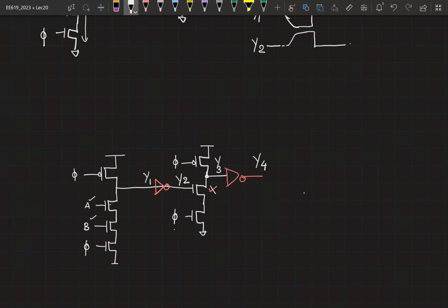So to answer that question, the question being asked is, this is anyways a NAND circuit that we were trying to implement. So if you have AND and an inverter here, it's already NAND. That is a very valid argument. I use this as a sample circuit. In actual cases, you have to imagine that the pull-down network of the second gate is something complex, right? So this is a very simplistic explanation being given. But the same logic you can apply even when the network here is something very, very complicated.